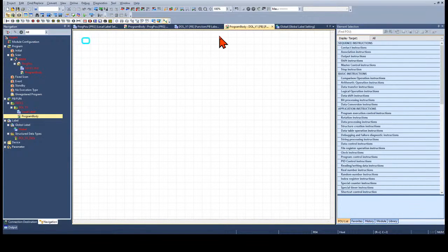So when creating your program, it's important to add labels, so when you go back to it, you remember what you were using in which rung. So we're going to start off by saying we want to write our piece of ladder to start and stop the conveyor. So this will be our direct online start and stop. Hit enter there, and we have a label to start off our program.